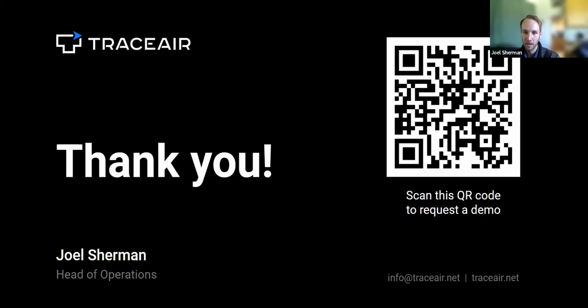How does groundwater affect LiDAR data? Okay, so yeah, water does impact. This is from Brad. Water does impact the ability for LiDAR to detect the earthen surface below it. So certain lasers have been designed to detect earthen surfaces through water, but for the majority of work that we perform, we do not use that type of technology, because it's just not frequent that we need to detect bathymetric data.